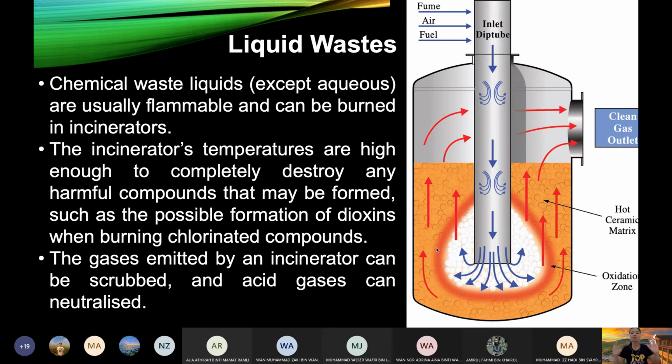So if let's say your liquid yang kamu hasilkan memang tak ada water and these are flammable, you can actually burn them in incinerators. Okay, so incinerator ni kenapa bagus? The temperature are high enough to destroy any harmful compounds that may be formed, such as dioxin when you are burning chlorinated compounds.